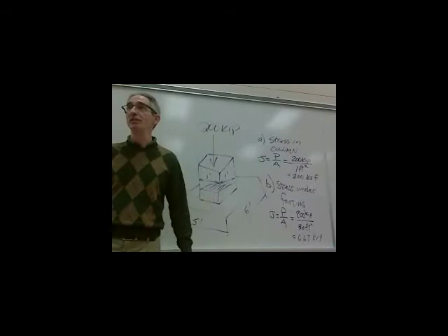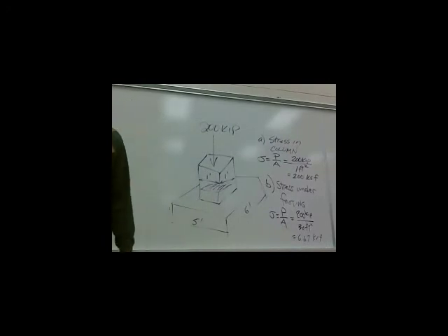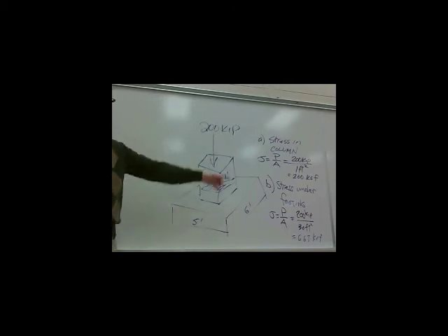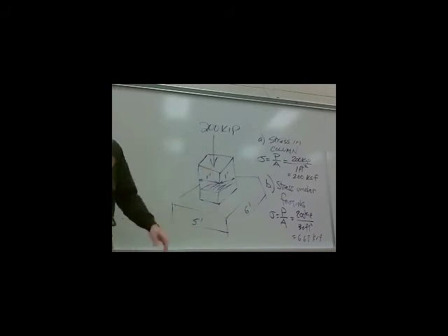Is that a big pressure? Huh? Not as big. Not as big, that's right. The answer is you don't know. I mean, it depends on what's supporting that. If this is soil, if this is like clay, well, 6.67 kips per square foot's pretty big. If this is limestone or something, limestone will be able to handle 6.67 kips per square foot. So again, right now we're just getting the mechanics of the calculations down. When you start getting into actual design, then you start, hey, this is big, this is not so big, and so on and so forth.